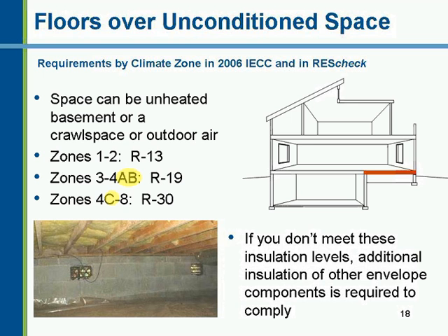If you don't meet these, and you're doing your takeoffs in REScheck, then again, REScheck is a trade-off approach. You need to compensate for not meeting the minimums and increase levels of insulation somewhere else in your exterior thermal building envelope when you're doing your takeoffs.